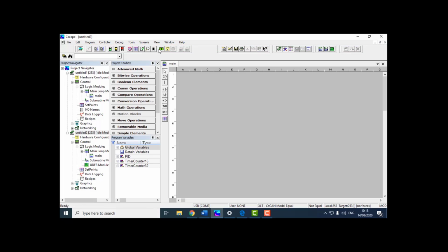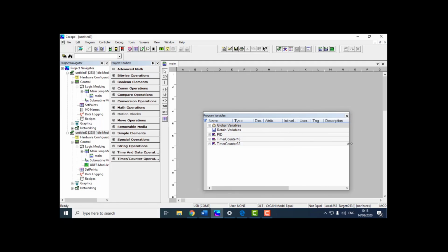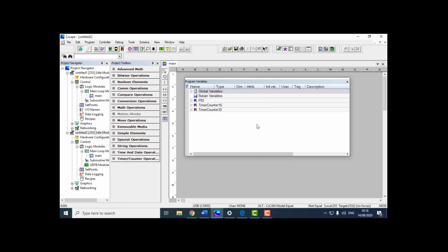The main difference is the Program Variables window. With register-based programming, we have I/O variables that we often have to use, but with tag-based, we've got this Program Variables dialog. Okay. For the moment, let's go take a look at the Program Variables window, as this is where we've primarily made changes in Service Pack 3.